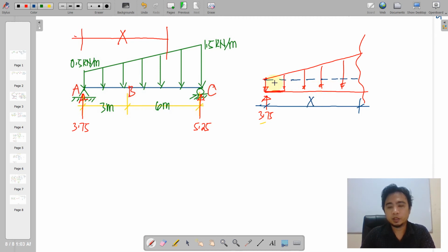We have a horizontal bisecting line here in order to separate two composite areas, the rectangle and the triangle here. This dimension is 0.5 and the other one is a variable. We wanted to express that in terms of y here, so that the height of this triangle is y minus 0.5. Then we resolve for this rectangular portion here, that is base times height, x times 0.5 is 0.5x.